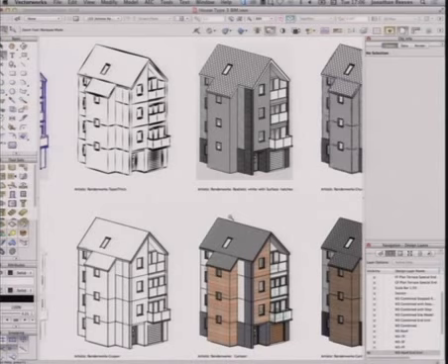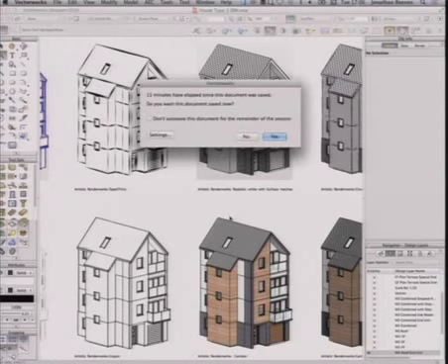I do quite a lot of refurbs as well. I haven't shown any today, but I do quite a lot of existing buildings with extensions. For that technique, I model in a slightly different way sometimes for the existing building. Sometimes the existing building is better modelled as extruded shapes because the walls tend to be all over the place. So you have a bit more control, although that's not the only method. And then you can create auto-hybrids of the existing building and then put it against the BIM, more BIM-ish modern stuff as well.